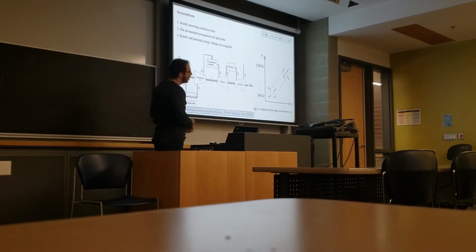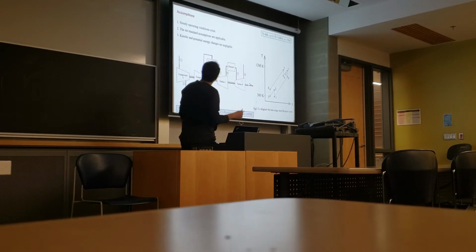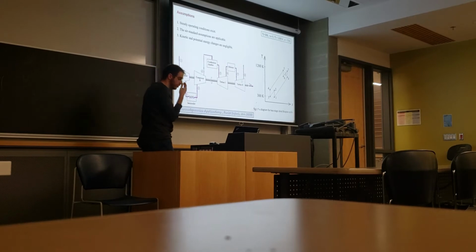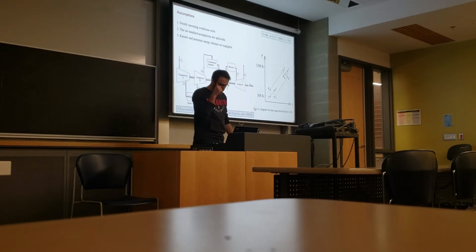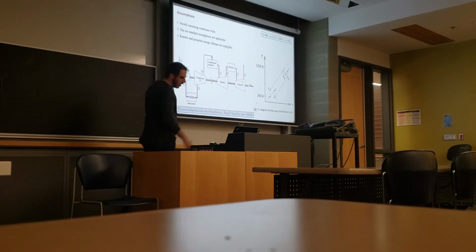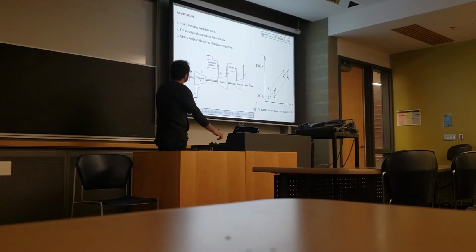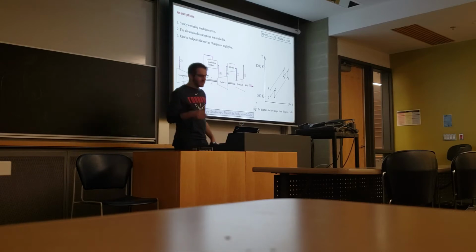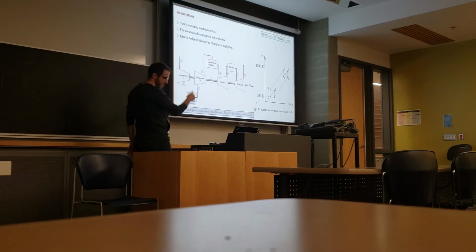The assumptions are usually the same in every thermodynamic problem you have as a cycle or a system. You have steady state operating conditions, meaning that the properties of the substance remain constant throughout the system.